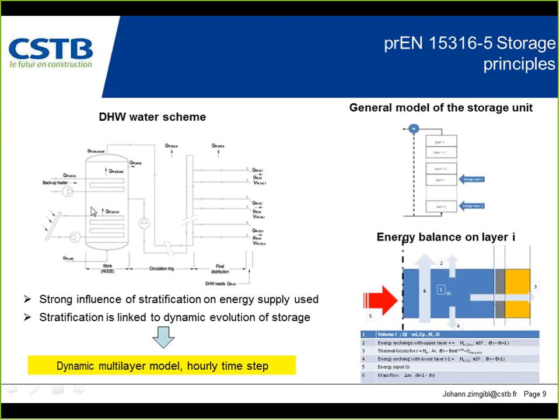So you see that it is not connected at the same height within the storage tank. And this has a very strong influence on the energy supply, because the stratification linked to the domestic hot water use is very important. This will have a very strong influence on the different systems used, for example, the contribution either from the solar part or from the backup heater.